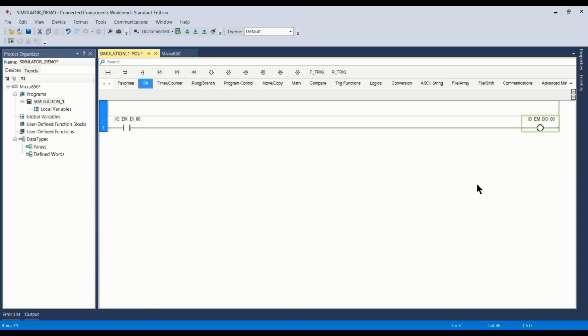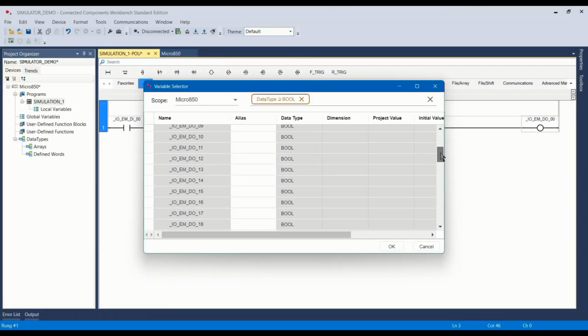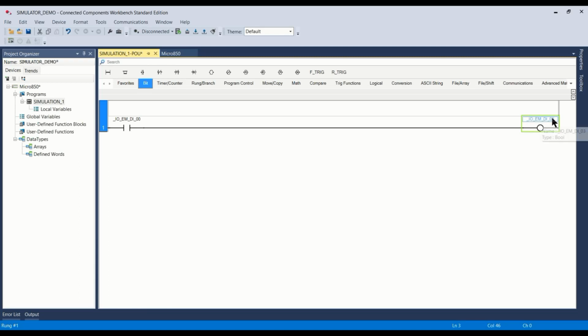So when you're doing your outputs, if it's a physical output, make sure that you use the drop down. It's a little easier. That way you don't accidentally, if you go to variable selector, it'll populate the same thing. Now it's gone to the default because I've already had that. But if you're not paying attention, you're selecting it, oh, I want output 3. It's very easy to select the digital input, and it doesn't appear there's a mistake until you go to build it. And once it does that, it says, no, I can't do that.